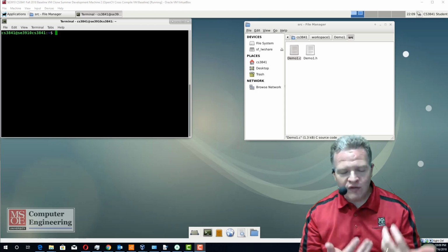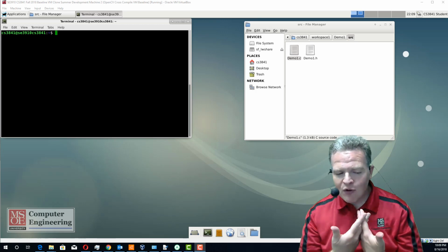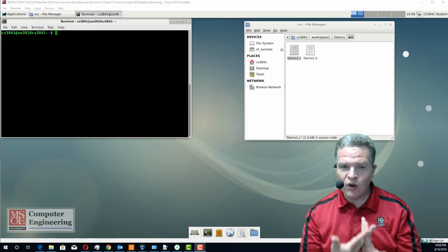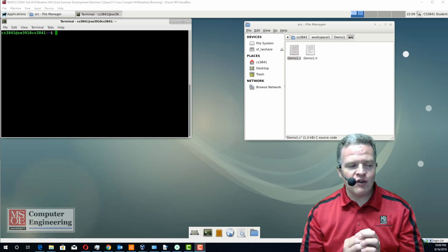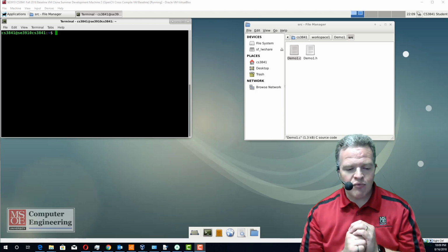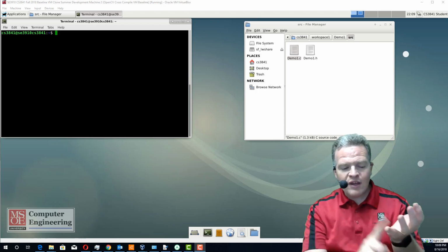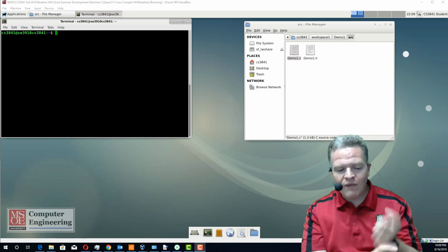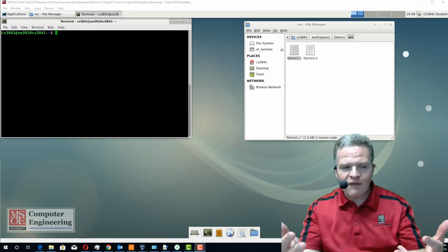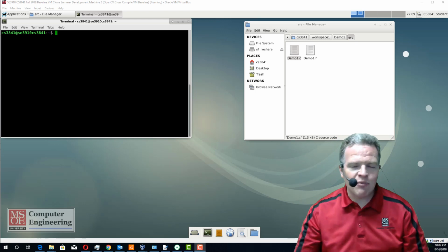It can be used in other environments and can be set up quite extensively to do what you want to do with it. So what I'm going to do is demonstrate with a very, very trivial Hello World type program how we import the code, select the C files, set the output, generate our make files, and set up our artifact type so that we can actually compile a project.